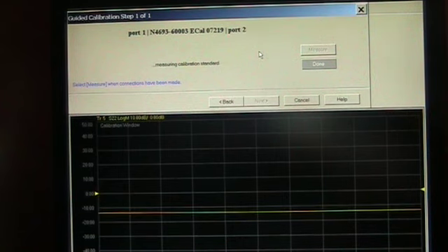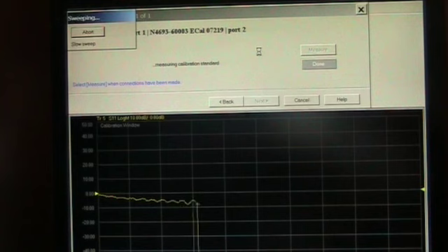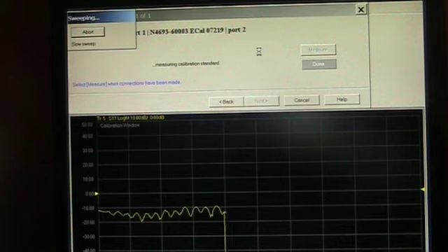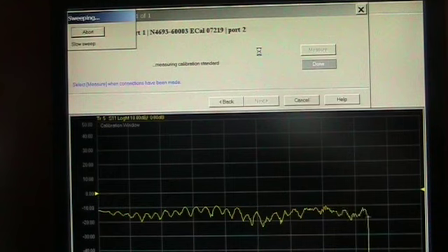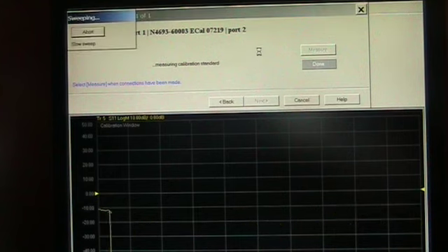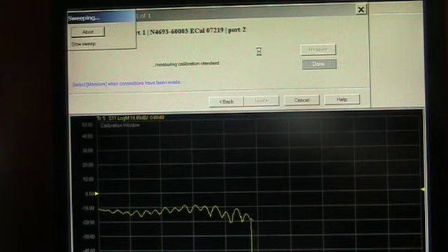This very much is just the straightforward at the end of the cables electronic calibration, nothing more. As we'll show in the diagrams later, there's reference planes that are created at the end of the cables, reference planes that are created either at the end of the probe tips or on wafer, and then what we'll have to do is create a de-embedding file in order to get us from one to the other.